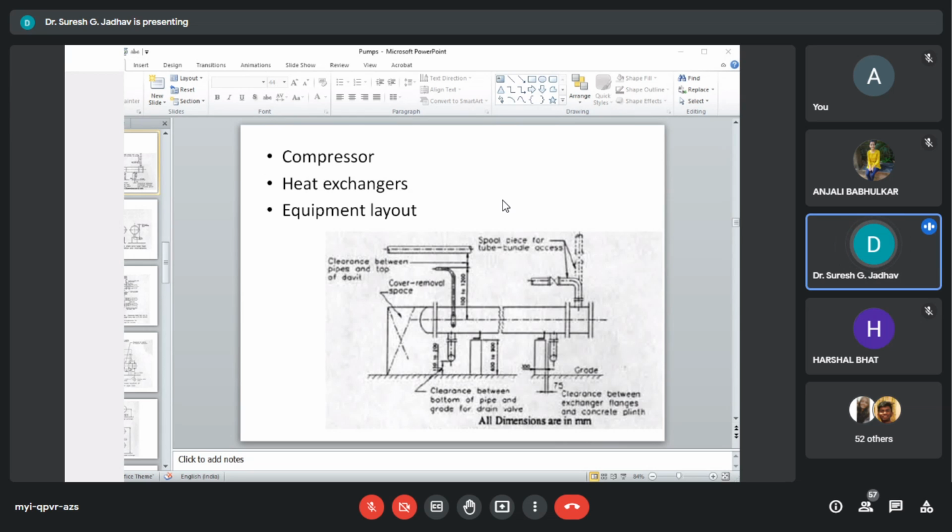To avoid condensate drainage towards the exchanger, the branch connection for steam lines is to be on top of the header. However, there is nothing wrong in having a steam connection from the bottom of the header if it is at the lower points.